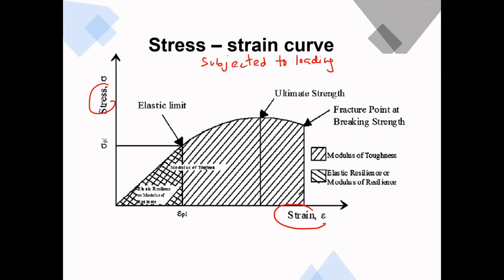When we subject a ductile material like mild steel to tensile testing, it will pass through various stages before fracture. If you still remember, the stages in a stress strain curve are proportional limit, elastic limit, yield point, ultimate stress point, and breaking point or fracture point.